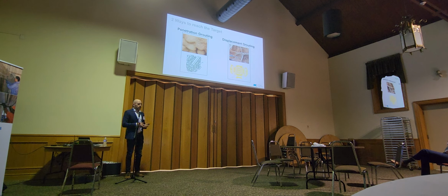On the other hand, you have this displacement method. What is that? This method is not even aiming to get penetration. The only aim is to displace the soil around the injection point by expansion of the product, not by pressure of a pump or something, by expansion of the product itself.